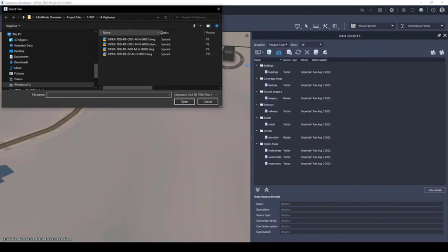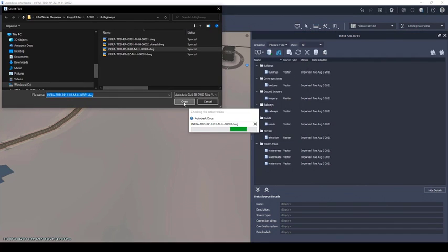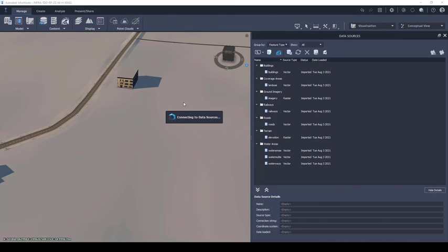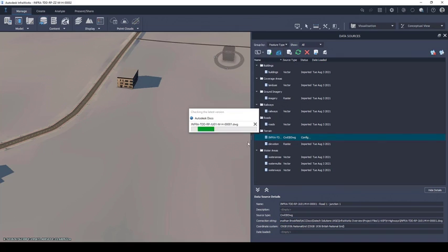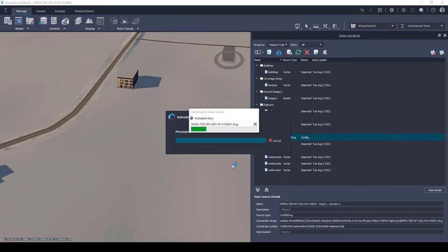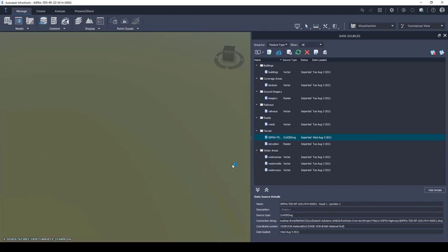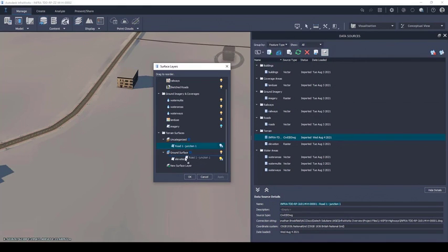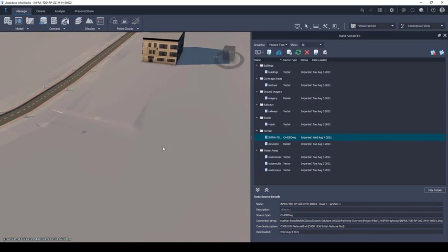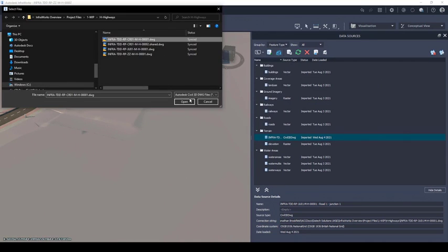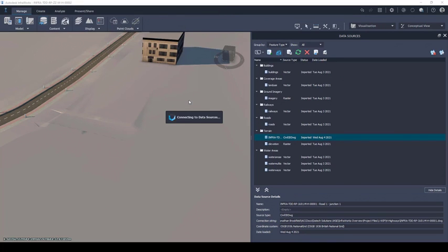Inside of our InfraWorks model, we have the ability to import proposed or more detailed topographical Civil 3D surfaces. The elevations from the Civil 3D surface will replace those found inside of InfraWorks using a hierarchy, triangulating between the two terrains at the tie-in boundary. This allows designers to quickly present their proposals in context and append other discipline models such as structural steelwork, architectural building shells, and so on, aligned to new ground levels.